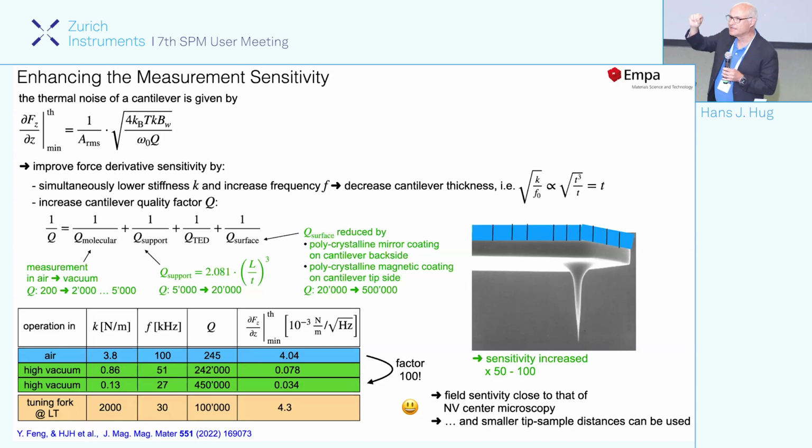So these are atoms that are not in a crystal lattice that you can nicely strain and destrain, but they are between lattice cells, and they hop like in an amorphous material, and that's causing dissipation. So what we do is we limit the coating to the very end of the cantilever. We coat the cantilevers with our own sputter deposition system, and we have a mask implemented.